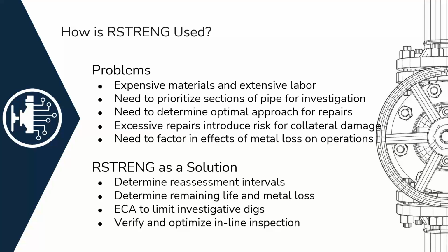We also combined it with to determine reassessment intervals, remaining life and metal loss. We could do engineering critical assessments to limit investigative digs, and of course, it's verification.